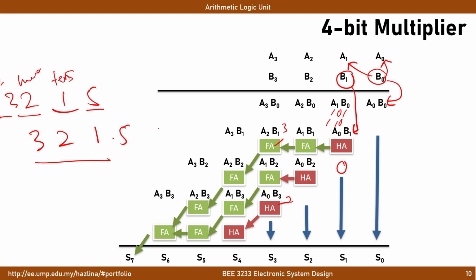Okay, spillover is like the one that I mentioned just now. When you have 1 and 1, you would have 1, 0. You have this 1 bit spill. Okay, this 1 bit spill you need to cater. So that is why, even though there are only 4 bits to add here, it requires at least 2 full adders and 1 half adder. Okay, the peak is here.